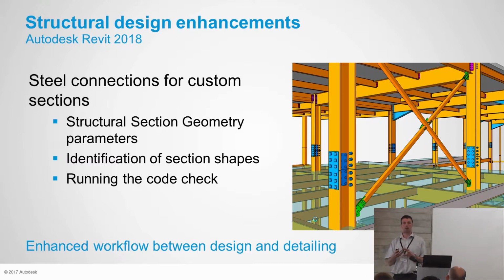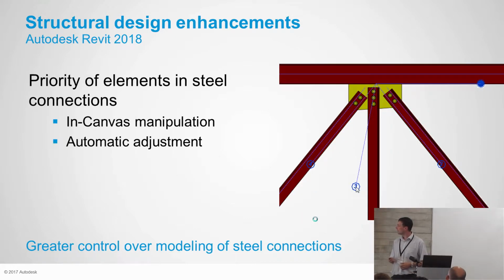Likewise, you can do something quite tidy and neat so that the fabricator knows that the architect doesn't want two great big bits of plates with bolts and the like. So I think there are uses for this, but not necessarily splashed across a whole model from a consultant side. I think Laura touched on it before, it's about modelling the right things at the right time. Not just because you can do it, don't just think, yeah, great, I can put splice connections all over my model, because that's not going to help anyone out.